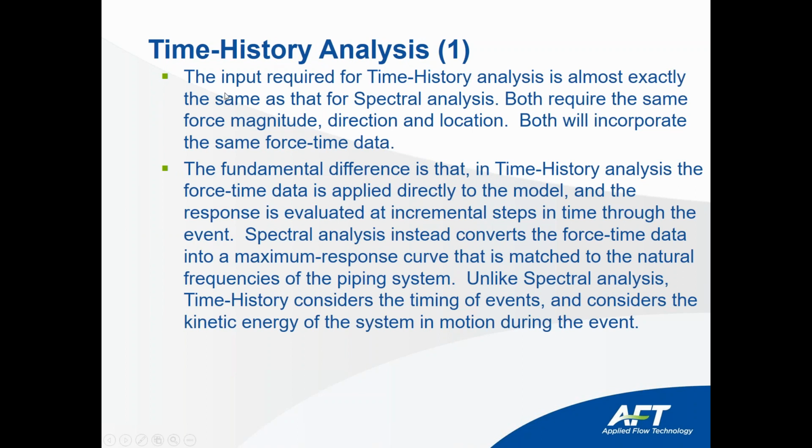Here you have to make a little bit more work. The input required for time history analysis is almost exactly the same as that for spectral analysis. Both require the same force magnitude, direction, and location. Both will incorporate the same force time data. The fundamental difference in time history analysis is that data is applied directly to the model.